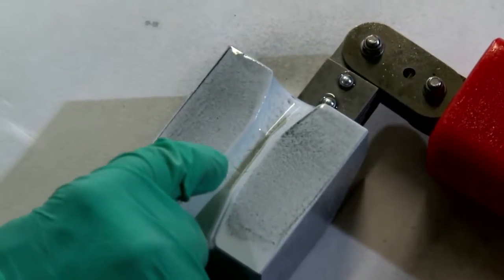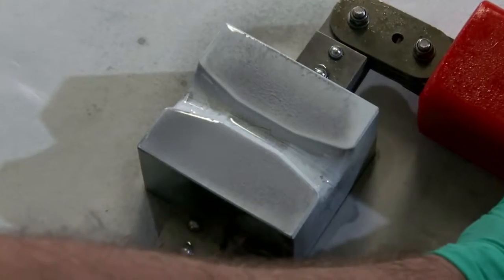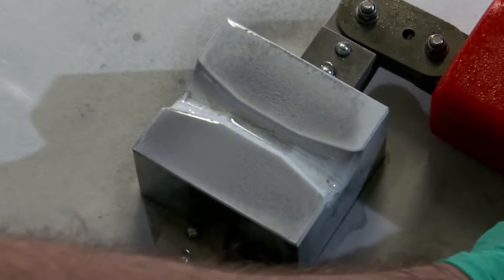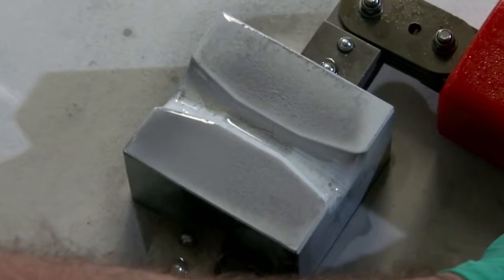If we'd have been testing this component in industry, because we've identified these cracks which are detrimental to the component, we'd just probably throw it away. If we didn't see any cracks, if it was deemed as good, then we'd have to make sure that we cleaned it off so that any materials on here are not going to contaminate the component for further work or its service life.